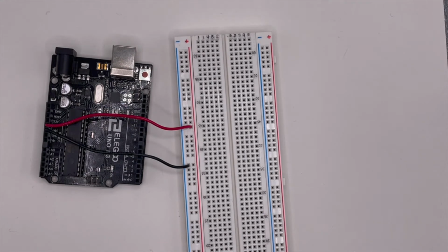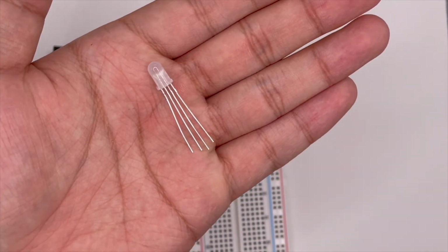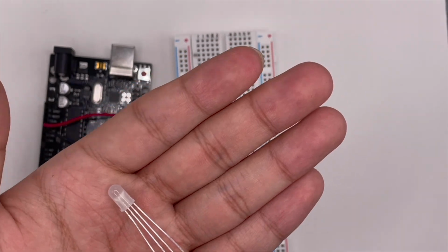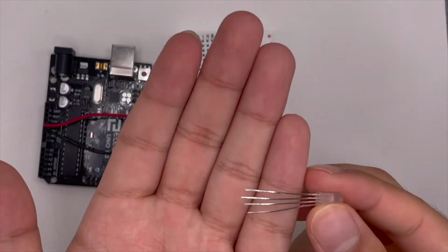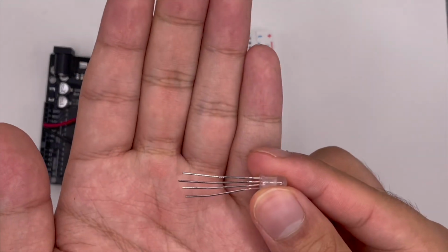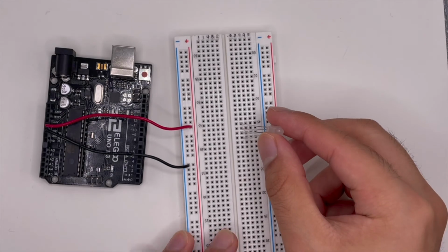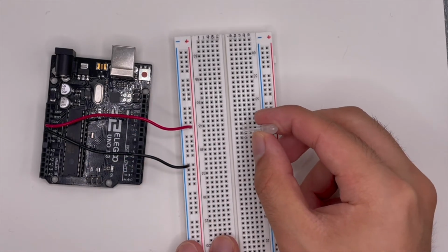After we do that, we can start connecting the LED. So if you notice on the LED, one of the pins is longer than the others, and this is the ground pin. So you need to keep that in mind as you place it on the board. Why don't you place the ground pin so the longer end is facing outwards like this. Once you place it inside the breadboard, you can go really anywhere, as long as it's on this half of the breadboard.